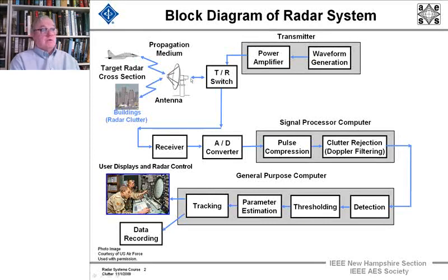And they will produce deleterious effects throughout this whole chain if not understood and dealt with appropriately with the radar, as a matter of things like choosing frequency in some cases, exactly how the Doppler processing or clutter rejection algorithms are developed, the dynamic range in the A to D converters, the spectral purity of the transmitter and the receiver, and also how the tracking algorithms are developed.